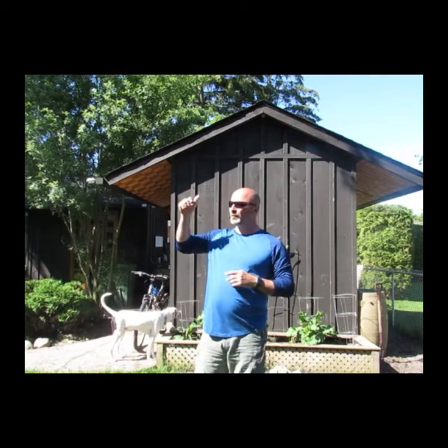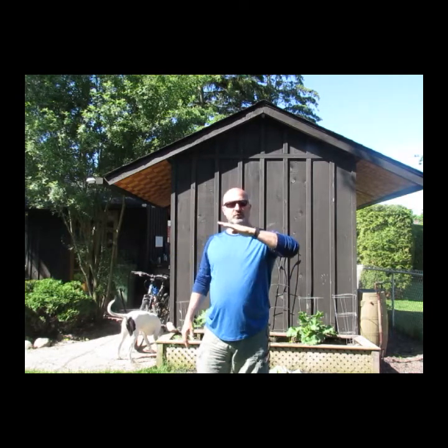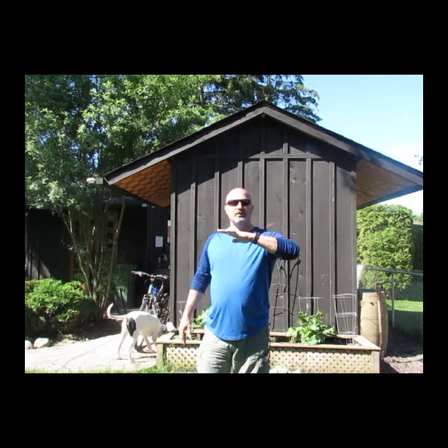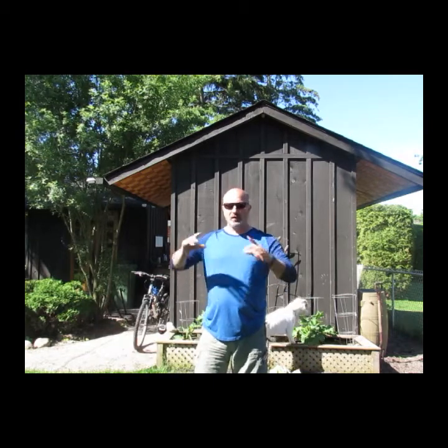When I was doing the blueprints for my shed, I looked online and it said if there's anything less than a 3/12 pitch, then you've got to take other things into consideration because it's too low. But it also had a lot of information about if it's greater than a 3/12 pitch, there are certain things you can do for internal bracing and structure of the truss itself.